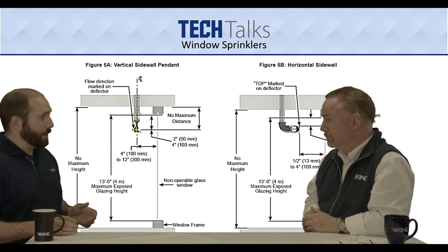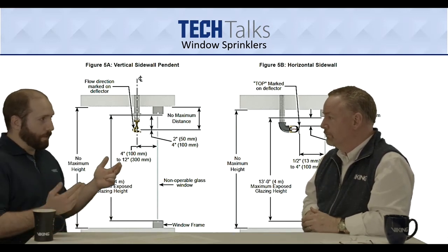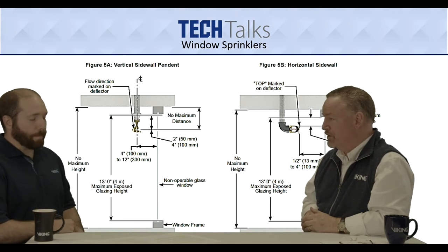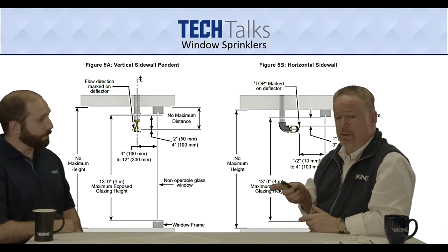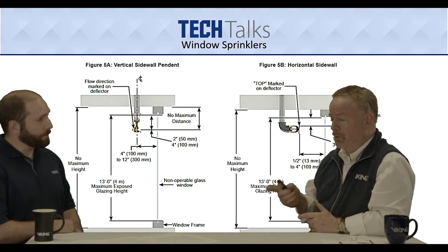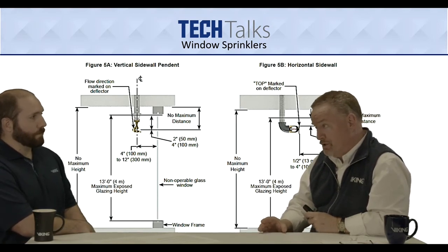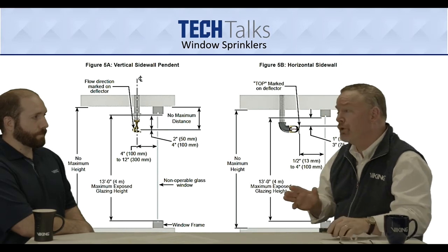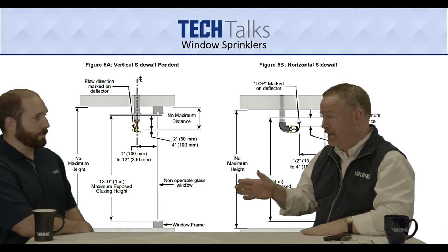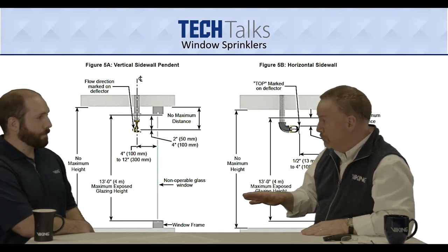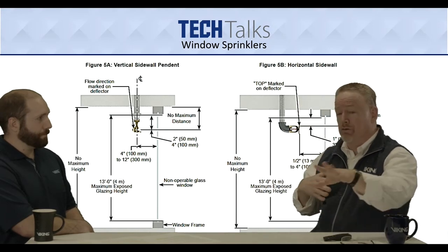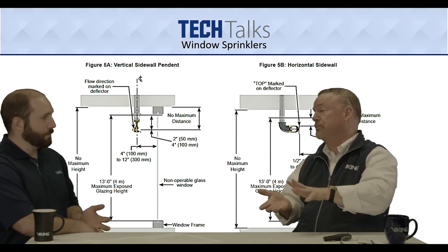In order to have that 2-hour equivalency, sprinklers are positioned on both sides. So that's great. But you also mentioned there that what's really important here is that evaluation, the ICC evaluation services report. And we didn't really talk about it. We said they needed to approve it, but we never really mentioned how you get proof that it's approved, right? How someone would know that this sprinkler was approved like that.